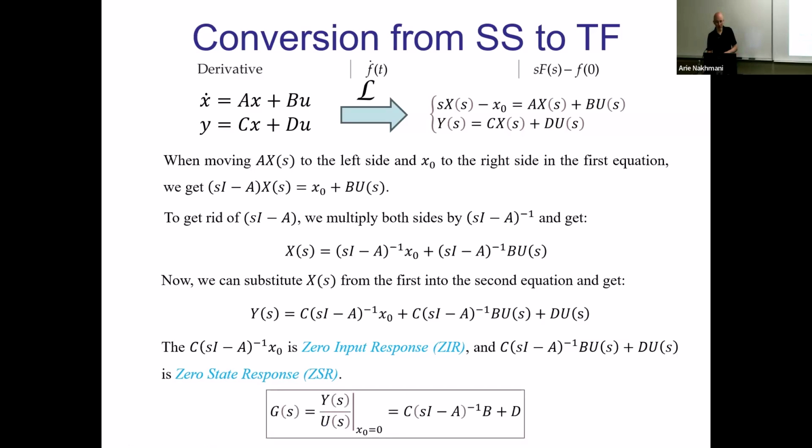And now we will move, obviously, to the transfer function, which is something that we wanted to find in the first place. We just take that u out of the parentheses here and combine that part with the D. This is your transfer function. This comes directly from here. I'm assuming that x0 equals the zero vector and dividing y of s by u of s, which gives the transfer function.